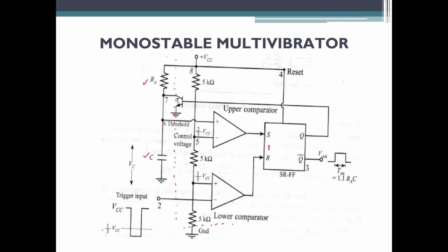That is, the voltage flowing here will be coming to this resistor, and as this transistor is on, all the current will be flowing through this particular transistor. Therefore, the voltage at the capacitor will be 0 and the output voltage will also be 0. Even though it is containing a data of 1, the output voltage, which is basically the output obtained at Q bar, will be 0.